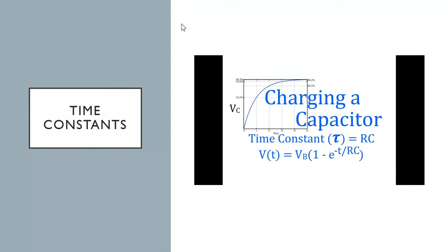So initially, the capacitor works as a short, right? It doesn't offer any resistance or doesn't offer any opposition. There's no forces trying to oppose the charges moving around. As time builds up and the capacitor becomes fully charged, well, then it's kind of like an open. It breaks that path. Once it's fully charged, that path doesn't exist anymore and no charges will move through that path, right? So it goes from offering nothing in opposition to completely stopping flow. But this takes time.